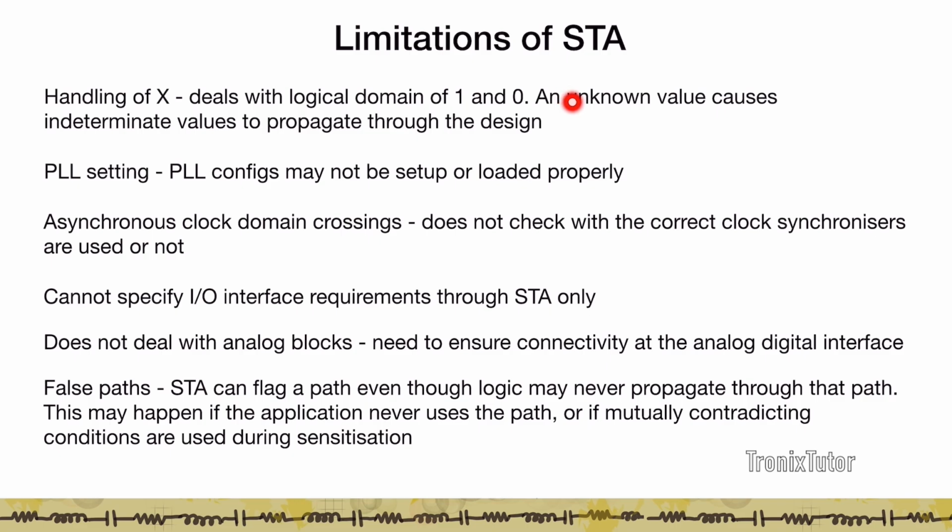An unknown value is treated as indeterminate, so it leads to propagation of indeterminate values through the design. If you have PLLs in your circuit, then the PLL configuration cannot be set up in an STA. If you have asynchronous clock domain crossings, those cannot be checked because we don't have correct clock synchronizers available.